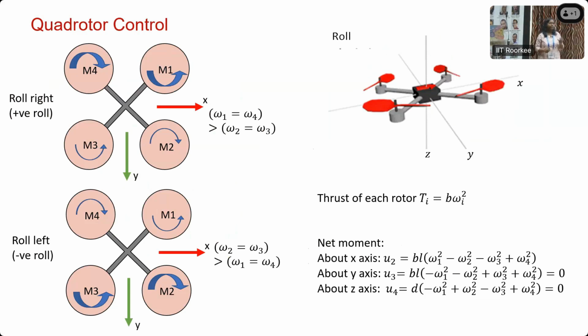So what we have noticed is that we have 4 control inputs. U1 is for controlling z, U2 is for controlling roll, U3 for controlling pitch, and U4 for yaw. So from here you can see that we are controlling the angles and the height. But if I ask you that you want the quad rotor to follow a desired trajectory, which means you have xd and yd, in that scenario how will we do the design? Because these control inputs are making phi go to phi d, theta go to theta d, and psi go to psi d. Basically that is what these controllers are doing.